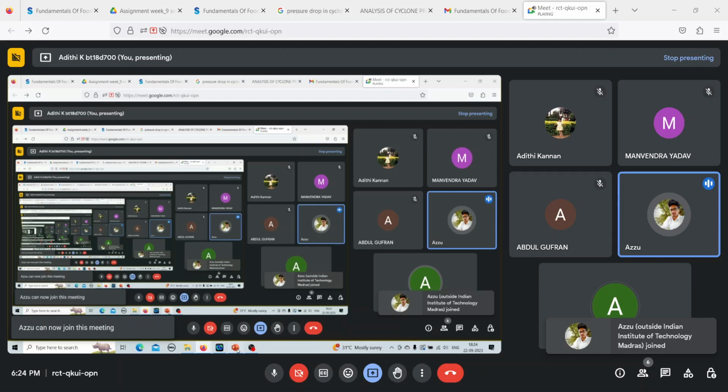And you have centrifugal filters also. So all these you cannot continue without scraping out the cake first. So at one point of time you need to stop the process, scrape out the cake, and then restart the process again. So all these are discontinuous type pressure filters, and that is what is used in oil mills. So the answer is option C here. A more pictorial representation of all this is discussed in the video lectures for your reference.